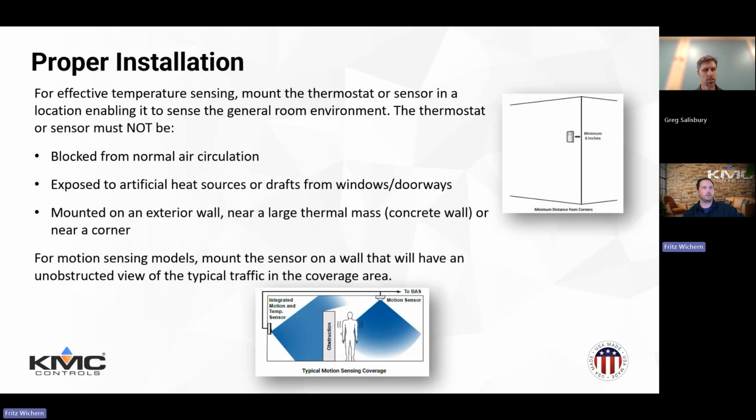Next, we're going to just take a quick look at it. I know a lot of y'all have heard this, so I'm not going to drag on about it, but it is important to remember the proper installation and how these sensors should be set up. You don't want to have it blocked from normal air circulation or exposed to heat from a radiant heater, drafts from windows, things like that. You don't want it mounted on an exterior wall.